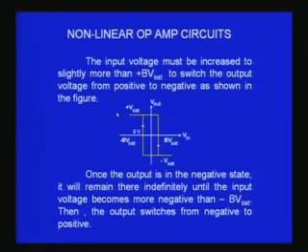Once it goes to plus Vsat, the V reference becomes plus, and therefore as I come back with the input voltage, till I come to plus V reference, there is no transition, only at plus V reference there will be a transition. Therefore you find in this graph it is traversed along this direction and it goes up, comes over here, and when it goes back it takes a different route. Therefore this is called a hysteresis.